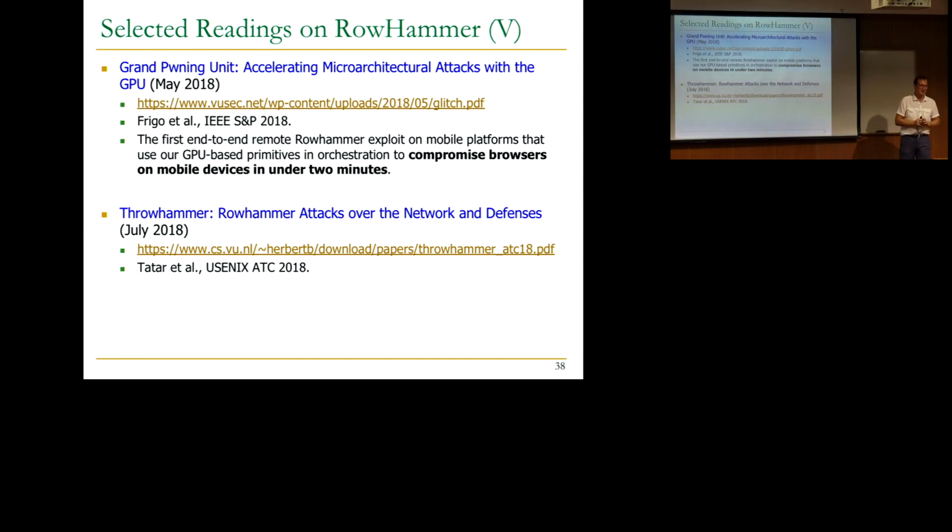So most of them are, I believe. But there need to be more studies, I think, for the current DRAM chips. Also, this problem has not been solved. Why study rather than correct it? You can easily have a form of cache in the controller, like an inverse cache, that doesn't allow you to hammer many times on the same row. Yeah, we're going to talk about the solutions. I think going forward, maybe that's one of the solutions, but what happens to all of the chips that are in the field? So you need to have some other solution for that. But I agree with you. I think the solution space is very important, but we're going to talk about that.